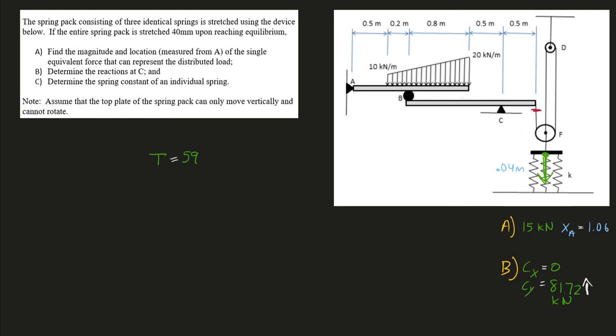We have this T. It's that 59. So all of this is all the same rope here. So it's activated with that 59 kilonewtons of force. And then we get down here. So the way I like to think through this is that we have this 59, 59, 59, 59. And then again that same rope 59, and then we have some sort of nail here.